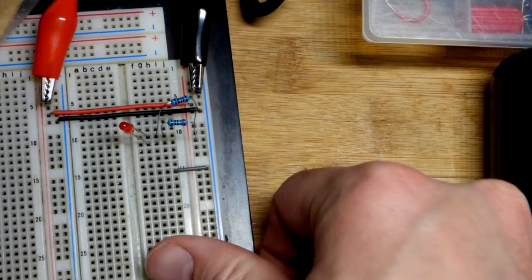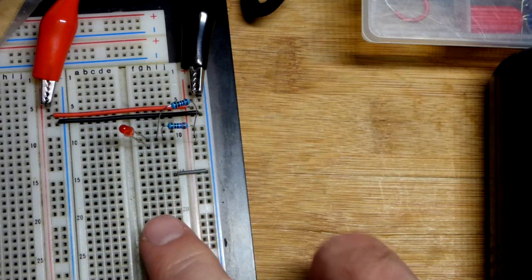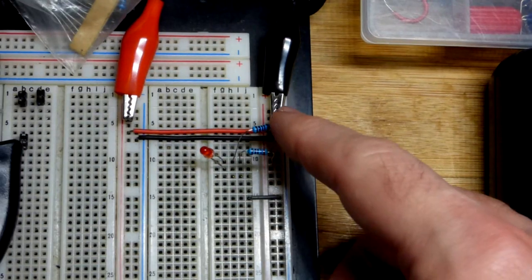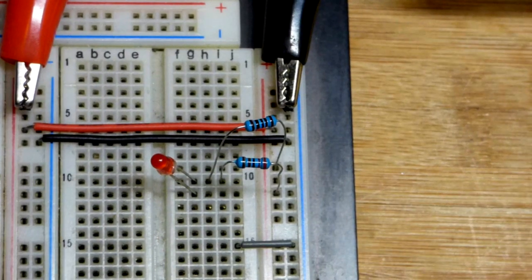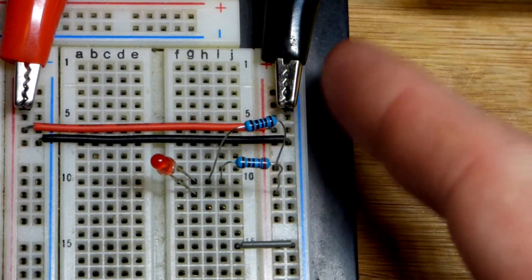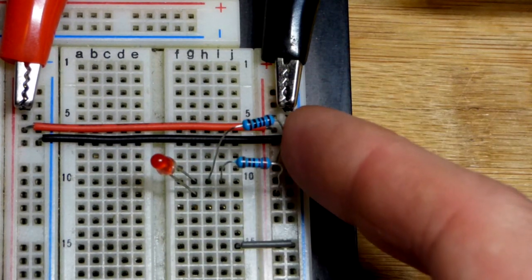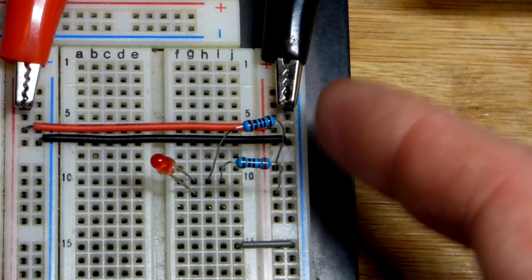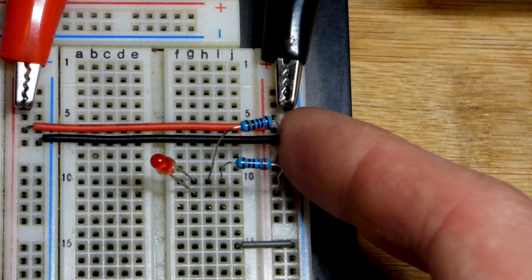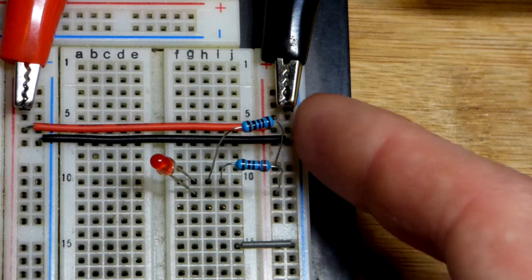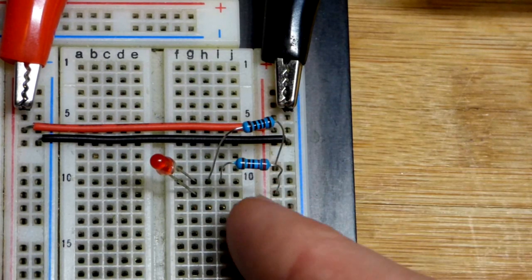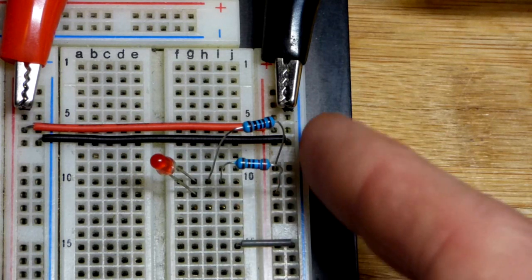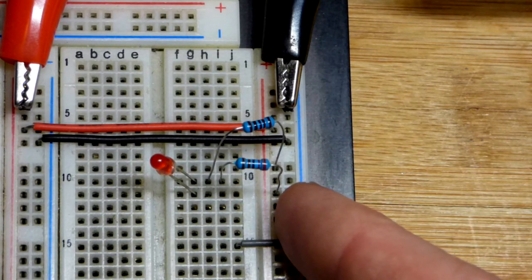But like I was saying when we were looking at the diagram, since this is a quarter-watt resistor, it will get too hot if we raise the voltage, get more current going through it, or whatever. Or if we use a lower value, it will get much hotter than you desire. So when you add resistors in parallel, each one of them is passing the current independently, so each one is creating its own amount of heat.